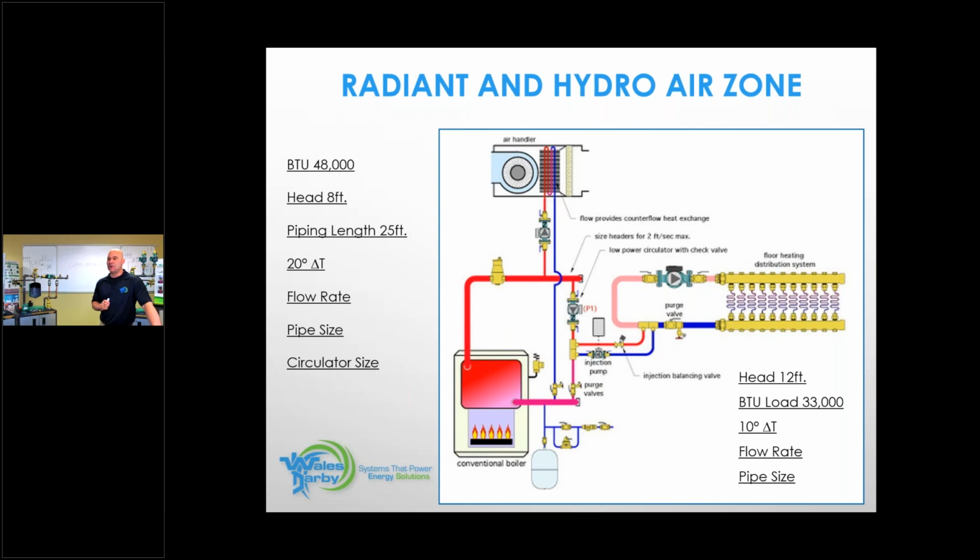How many times do you go to an air handler like this and it's piped with 3/4 inch pipe, which really only carries about 40,000 BTU. So on near or design day, you could have short cycling of the blower because we're losing temperature too quickly, because we're not delivering the BTU to the air handler that's needed, which would be an insufficient heat call.